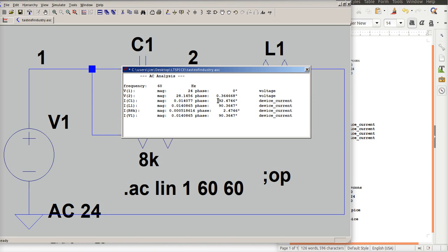And these are actually the phase shifted, or the angles that those currents would have had. So in the AC circuit, you talk about a magnitude and you talk about an angle. That's important to remember: if you're measuring or analyzing a circuit with a meter, it's not going to show you the phase angle. It's only going to show you the magnitude. So that's sort of the values you want.